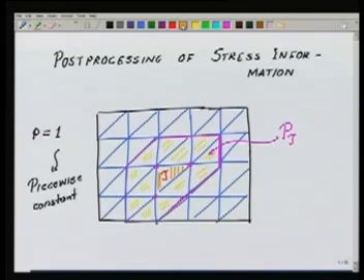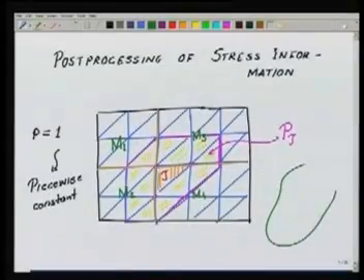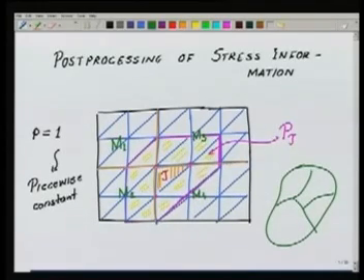Let's say that in this domain I had taken a different material in each of these parts. That is, I will have here material M1 in this region, material M2, M3, M4. Here we have taken the boundaries of the material domains to be nice straight lines. In general, they need not be like that. When you have a multi-material domain, you will have a domain like this with different materials in the various regions. In that case, what should you do? You should make the mesh in such a way that the boundaries of the material domains are honored. That is, the elements do not cut across the material boundaries.